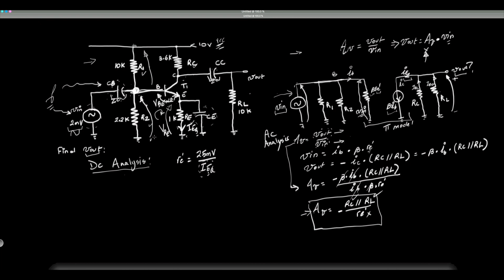Well, what is this one here? If you think about it, here's VCC. Here's R1. And here's the base. Here's R2. Here's the ground, and we're going to the transistor, right? We have to make some assumptions here. And so VCC is the voltage from ground to here. And we're interested in this point here. Let's call it B. So the voltage across R2, we're going to call it VB.